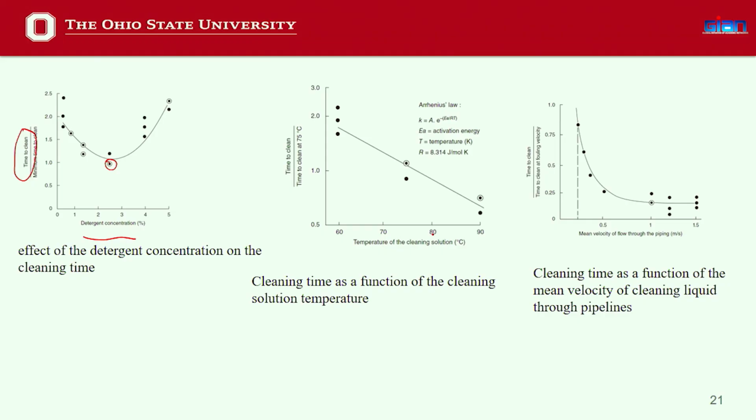In the same way, when you look at the temperature of the cleaning solution, you can see how much time it takes to clean. Generally, the time decreases with an increase in temperature. And of course, you have to make sure that the components of the equipment can tolerate the temperature, all those things. So, you have to keep that in mind.